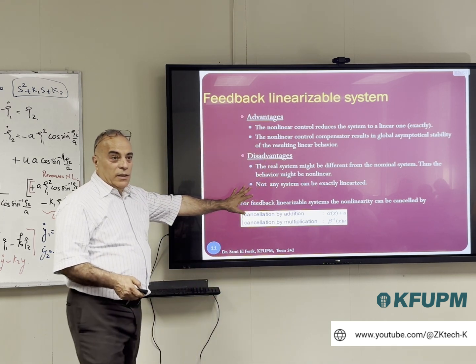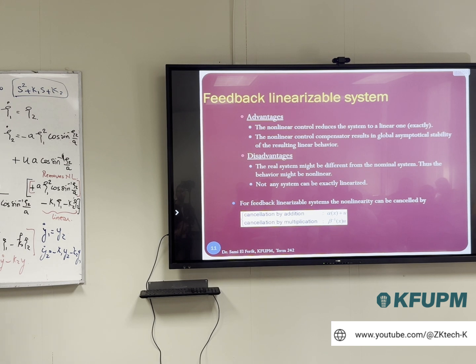This one I will show you today how to deal with. Sliding mode control is almost the same thing as feedback linearization, but assuming the worst case of the difference between the systems. So we'll see this later in the sliding mode. But for this system here, we are saying that the system can be complex. It can have a nonlinear controller, two cascaded controllers, but it's maybe better than making linearization over 20 points or 1,000 points.